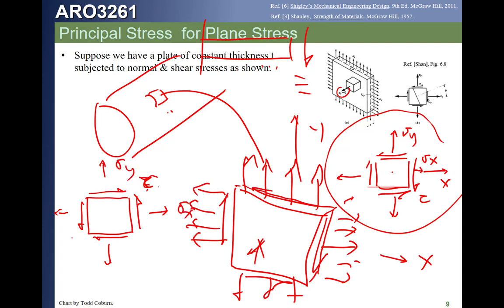And if we draw tau anywhere, since these are the same, then that means we know what all these taus are, right? On every face, they've got to be the same. So you've got to be alert to the sign convention for shears. Usually we're going to call this sign convention positive for a little shear element, while we're still going to use this chopping off the beam positive for a beam element. Okay, you're going to have to be alert and not miss that.